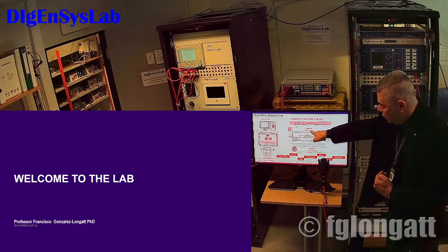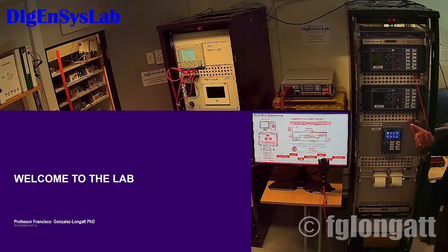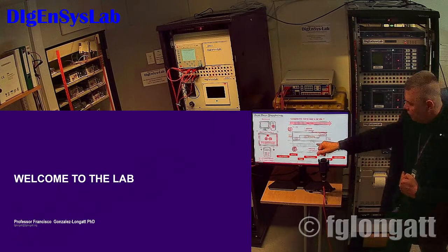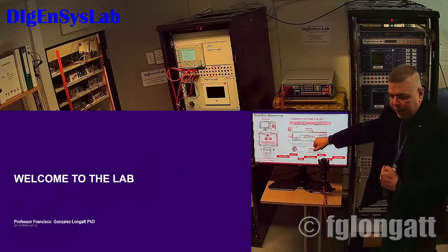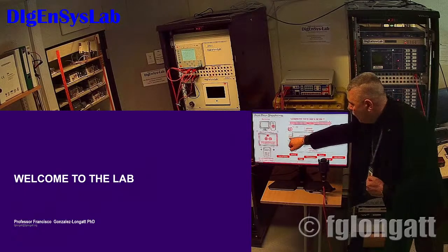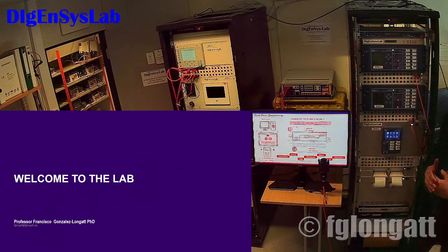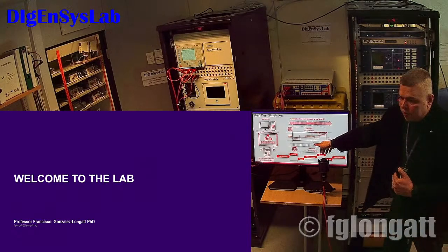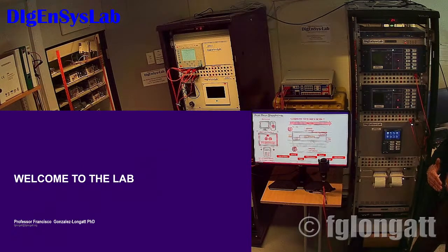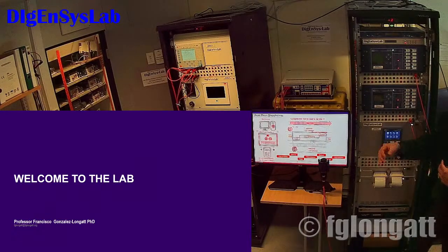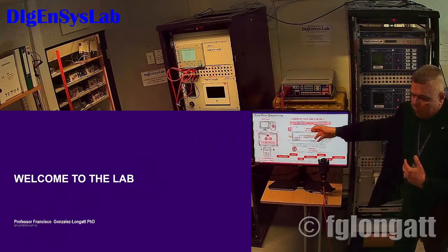And for instance, in a classical real-time simulation, we are talking about time steps of microseconds. That means that you have around microseconds to do many things. For instance, receive the data, process the data, and then send the data. Okay? This is for the CPU. And then you have the FPGA, because there are some processes that are faster than others. For instance, if you are doing power electronics, you need to use the FPGA, because the time scale is very small. We are talking about nanoseconds. And if we are taking measurements, if we are collecting data, we are using the CPU. And that is microseconds, okay?